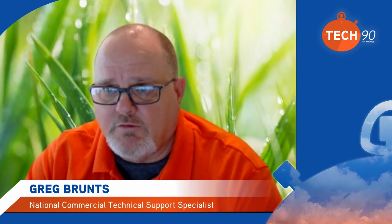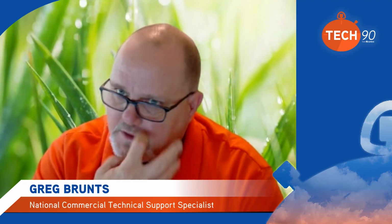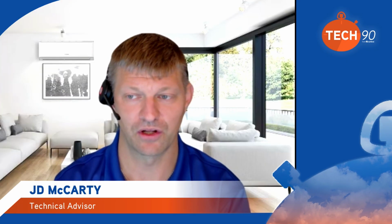On a mini split, though, they have one EEV, and it's going to cover your flow for cooling mode, and the EEV is also going to cover your flow for heating mode. Okay. So anyway, I do believe it does show you what position that EEV is in on that mini split service tool. Yeah, it's up to like 480 steps, but it'll tell you what step it's actually in. You can watch it open and close. The EVs that GREE uses are from 0 to 480 steps.